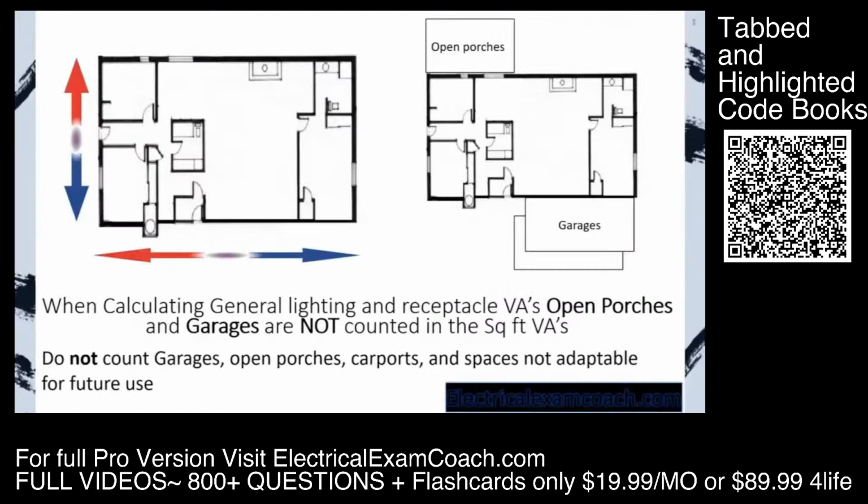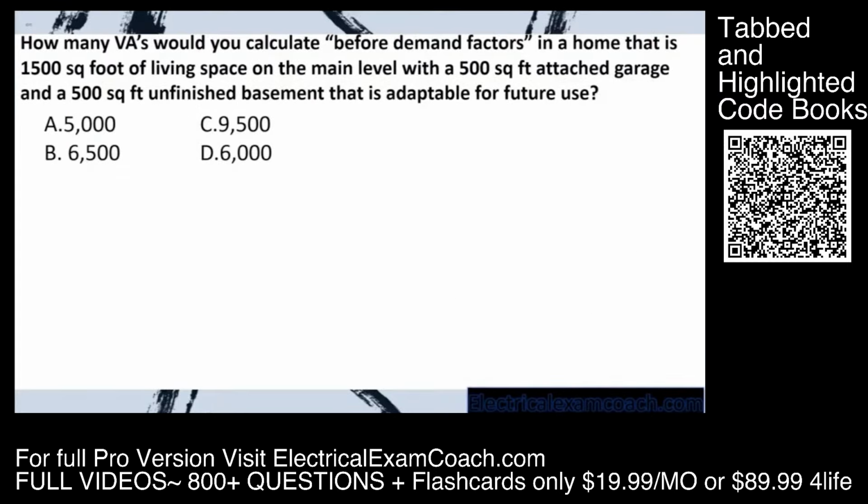When calculating our general lighting and receptacle VAs, open porches and garages are not counted in our general square foot VAs. We do not count garages, open porches, carports, and spaces that are not adaptable for future use. How many VAs would you calculate before demand factors?